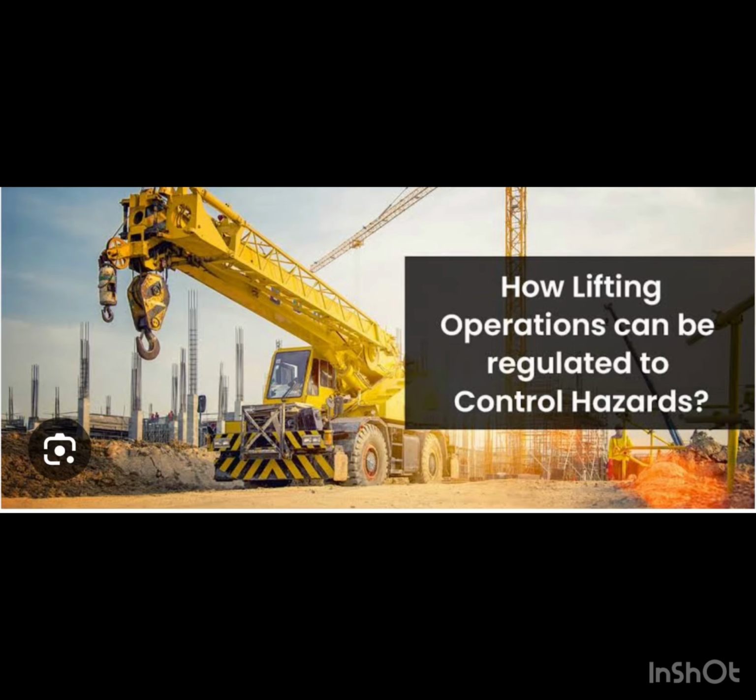What are the control measures for lifting? Permit to work, lifting plan, third-party certificate of equipment, third-party certificate of crane operator. Only trained and approved rigger shall give the signal, position the crane away from the adjacent structures, preventive maintenance of the cranes, daily inspections, barricading and signboard.